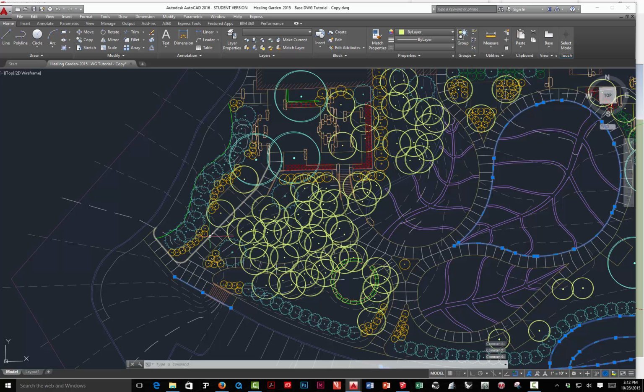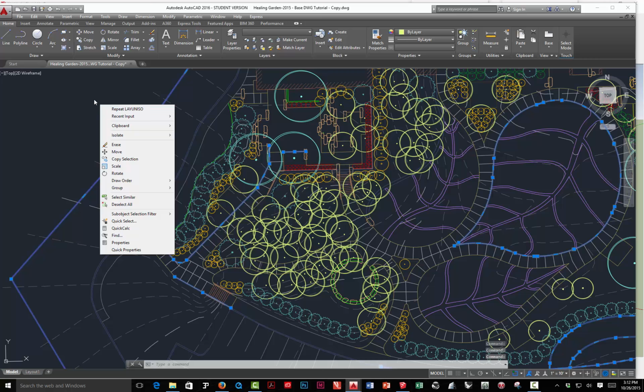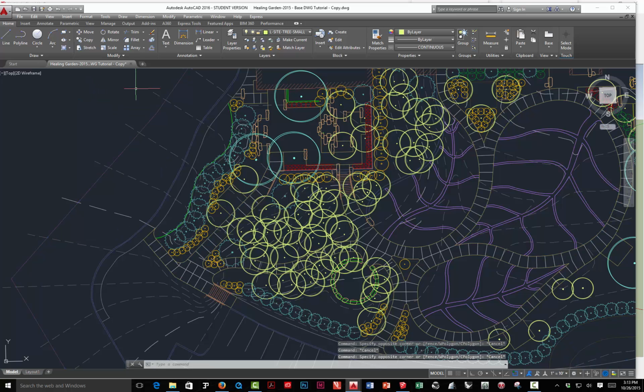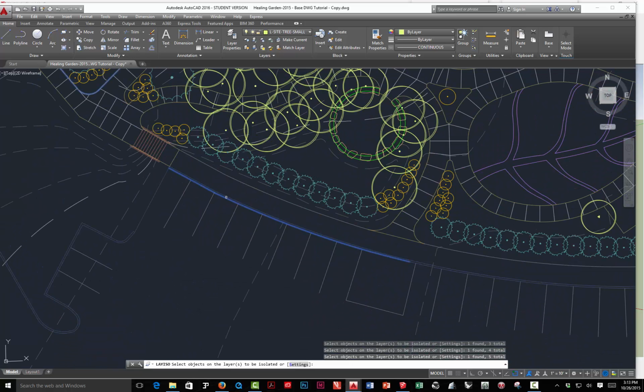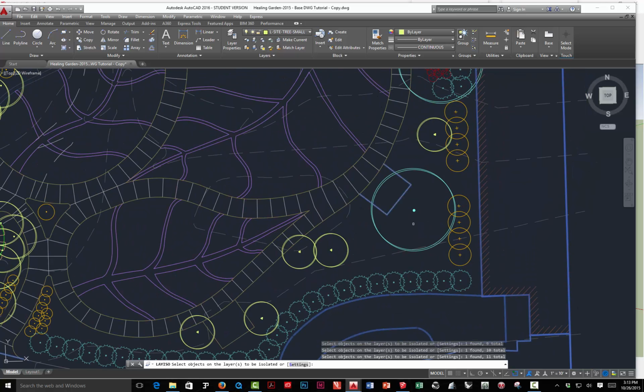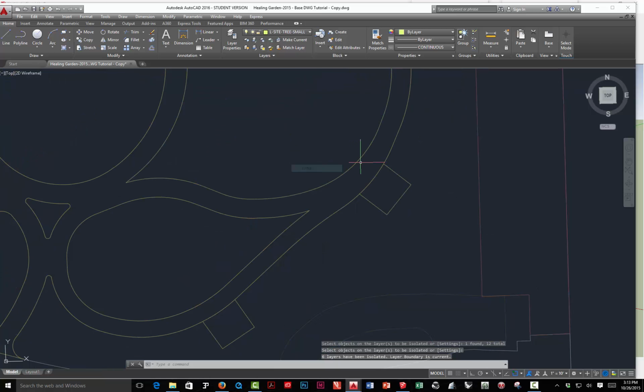Again, most of these, all I need to do is select one element on the layer with the layer isolate. Boundary line. All right, I don't know why this keeps happening. I just did this a minute ago. Let's try this again. Didn't have the tool selected. Isolate. Again, edges of pavement. These seating areas. To get the curve down here, it's part of the ground plane there. And again, just for good measure, if I'm not sure, I'll just click on another one. Edge of the building kind of forms that boundary on the outside, so I want that. Now let's try that. There we go.